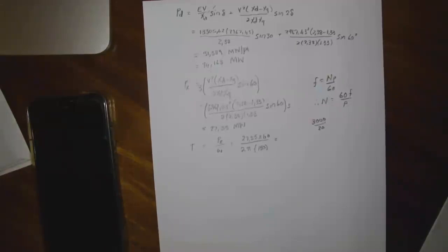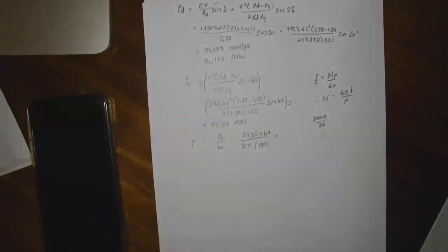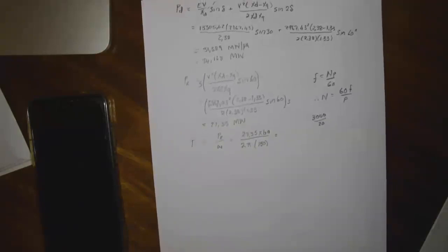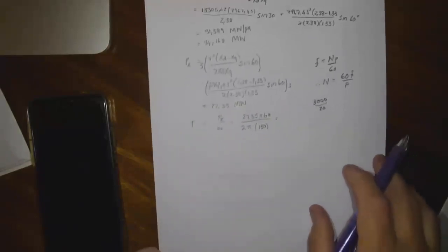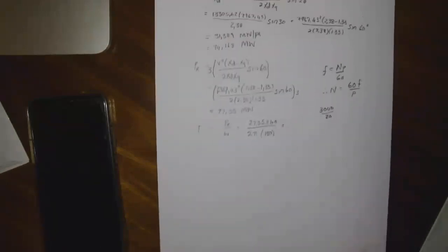Now the question I have, sir, is that when calculating your load angle, you're going to need load angle even though you do not have excitation anymore. So do you still go through the route of calculating E? No. In essence, okay, how do you do it?